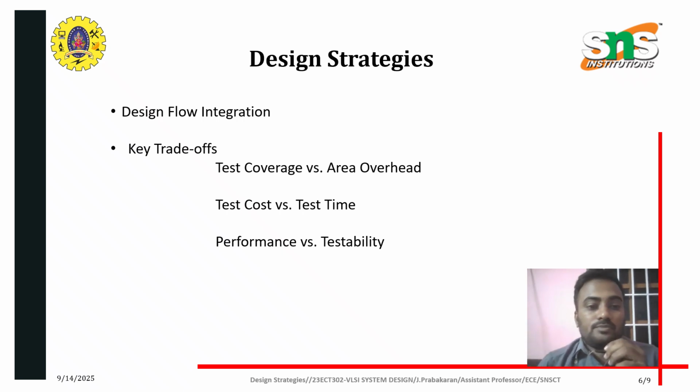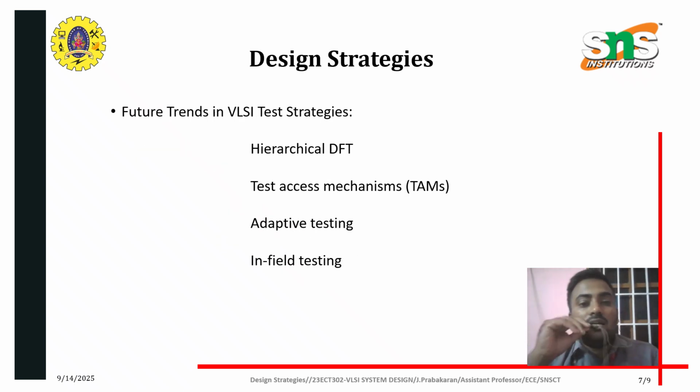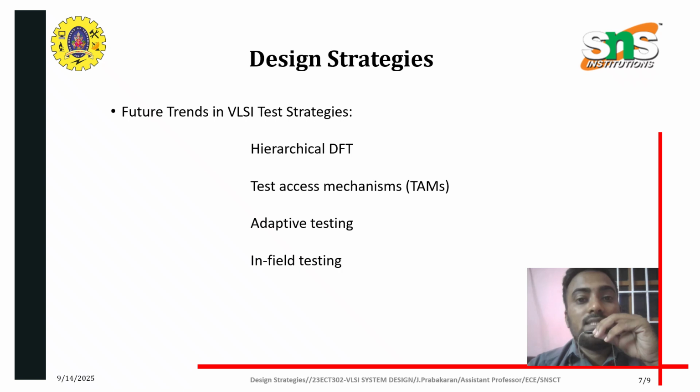And the next thing is future trends in VLSI test strategies, which are hierarchical DFT for large SOCs with multiple IPs, test access mechanisms in 3D ICs, adaptive testing, and in-field testing.